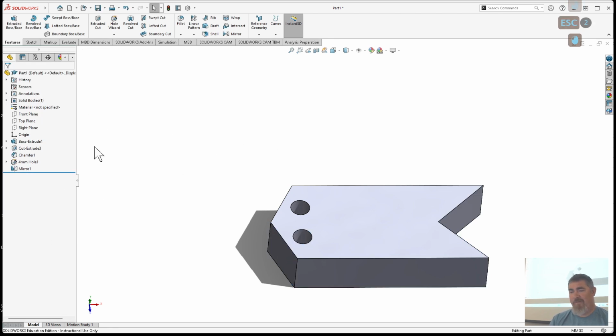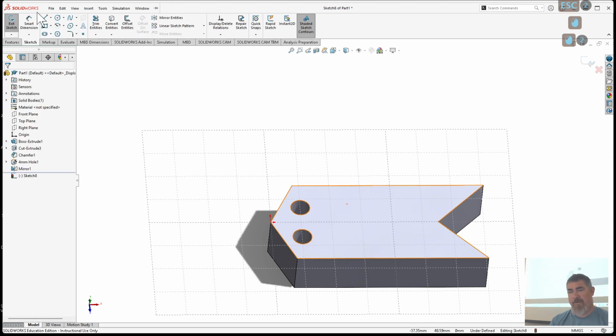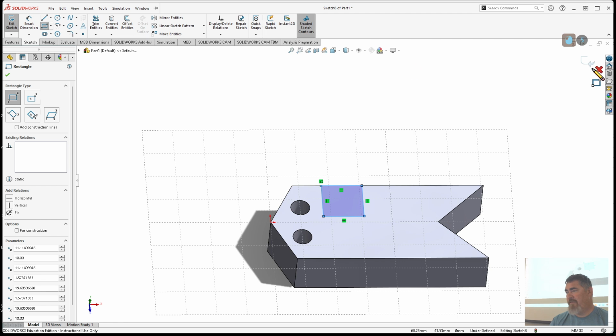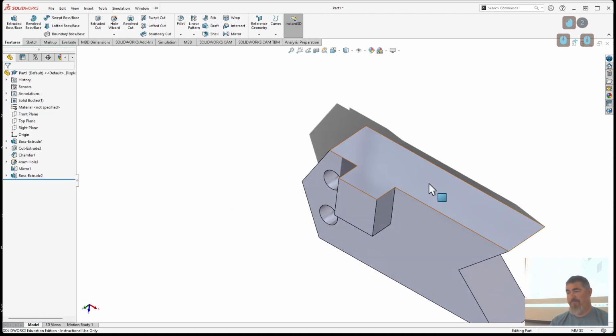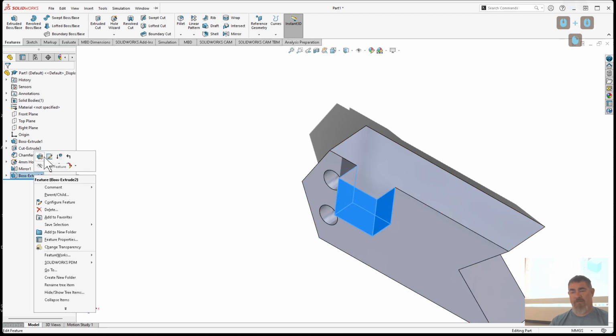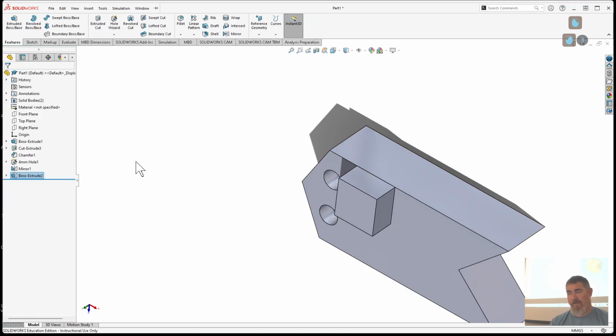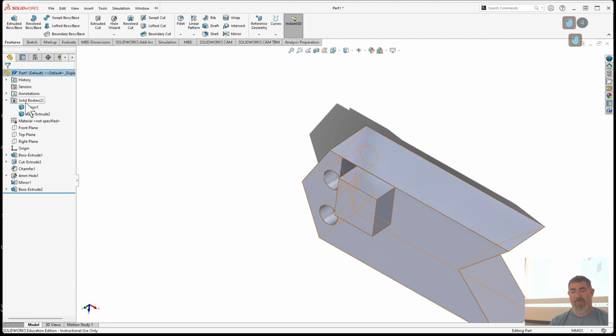So when I extrude things, I'll pick, draw something, and you can see the option is merge results. So we want to merge the result so that way it joins together. If you have merge result turned off, now it creates two different bodies here that are not the same. So our file here in SolidWorks is the same as our component in Fusion. Each component that we have in Fusion would be a different file here in SolidWorks. Okay?